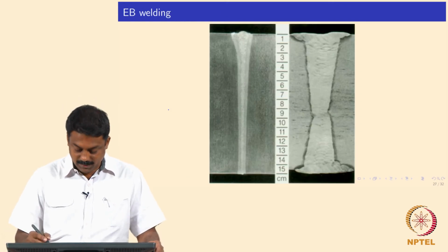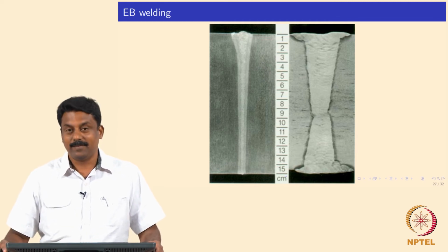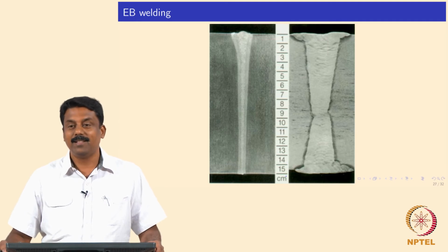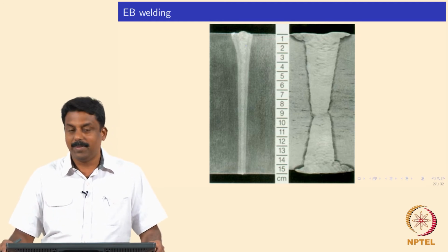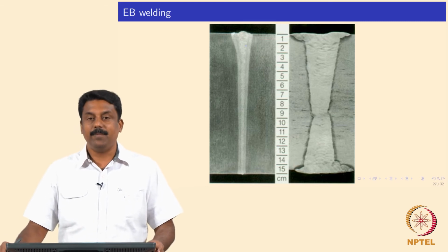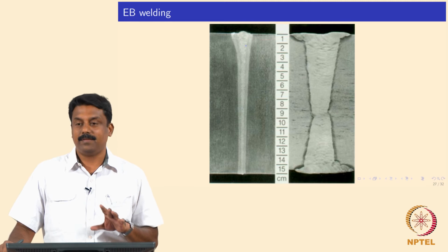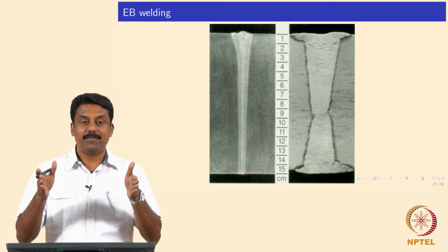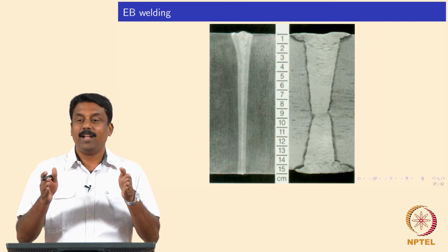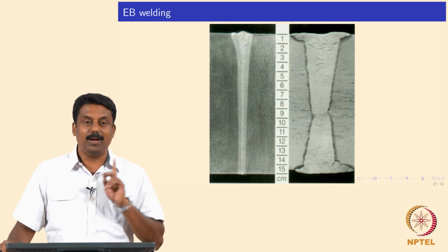So, what you see over here, this is 15 centimeter, it is not millimeter. Okay. So, that is 150 millimeter, and you can achieve a full penetration of 15 centimeter, 150 millimeter of steel, okay. And you can have a complete penetration in a single pass.